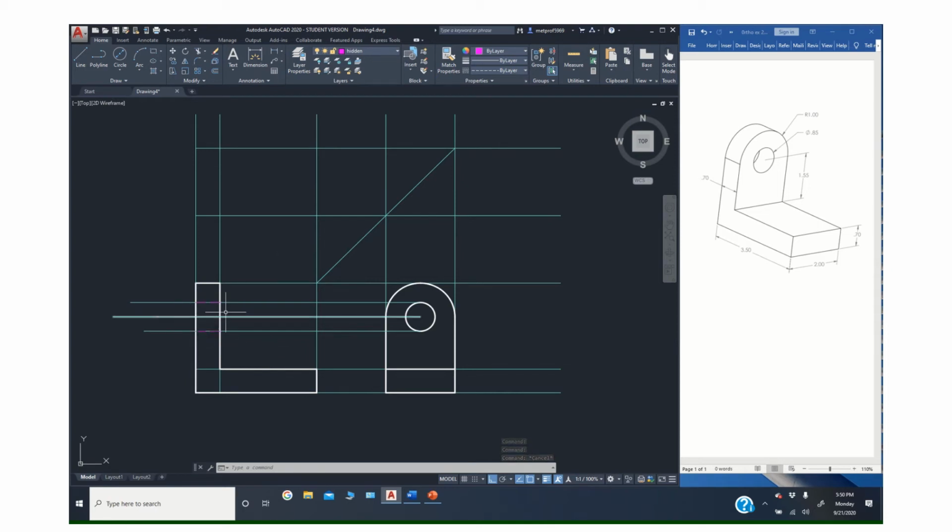Remember, the center line extends out beyond the edge of the part, so I'll do an offset here. Let's try 0.5. It has to do with the scale of the part. It would look silly to have a center line that extends too far out, so I did a 1/2 inch offset because this part is like 0.7 thick. There's no exactly right value for that. You'll know if it's too long, or I'll tell you if it's too long. Kind of get used to that.